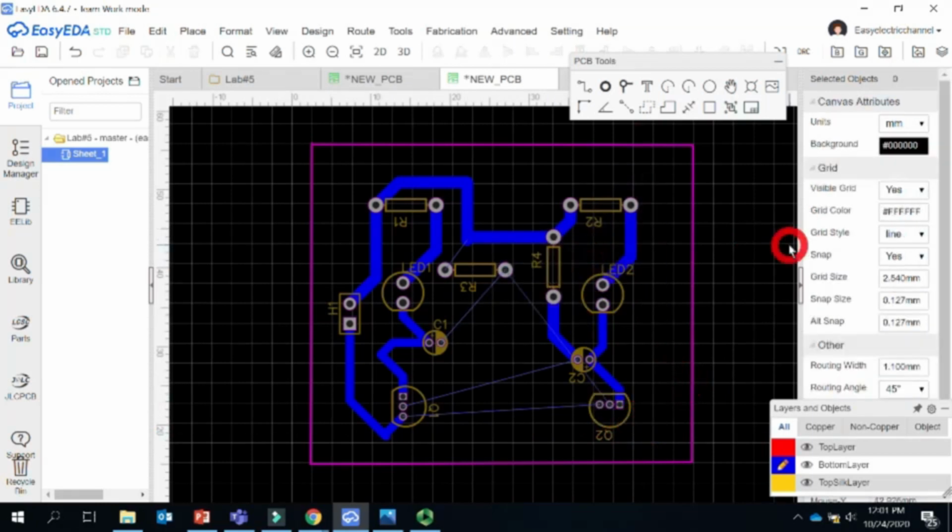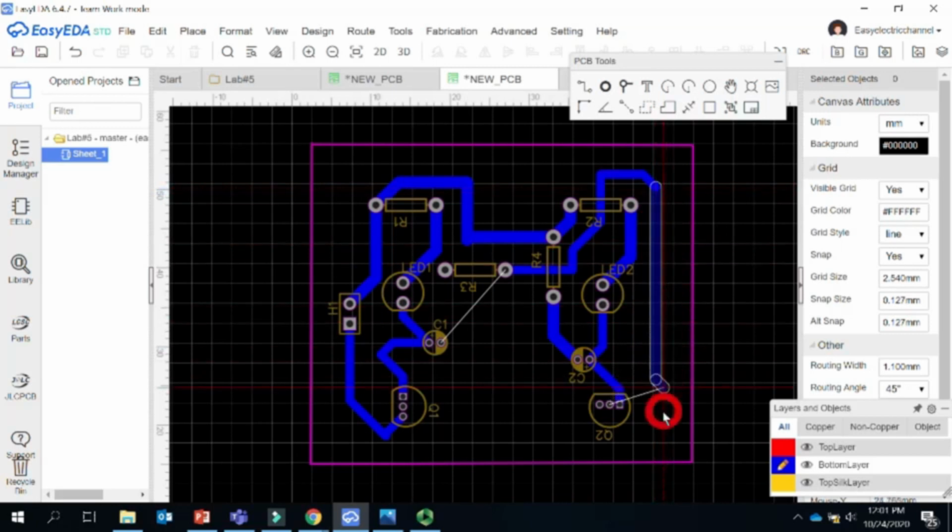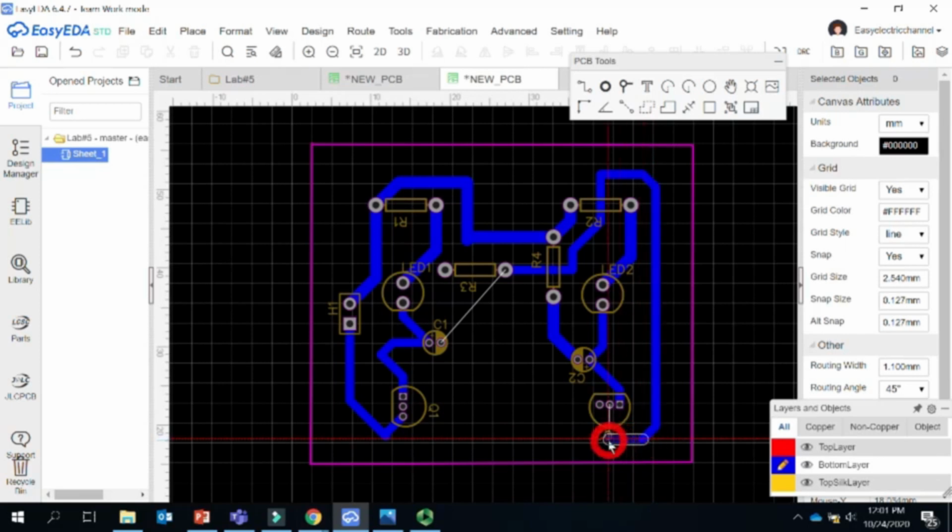So yeah, the reason I put 1.5 is that it makes putting the tracks more tough because you have less space. So if you have any problem with that, you could actually change its size, at least to less than the 1.5 that I selected. Whenever it's 1.5, it gives somehow a hard time to the connection, but we solved the problem. So the rest should be easy.